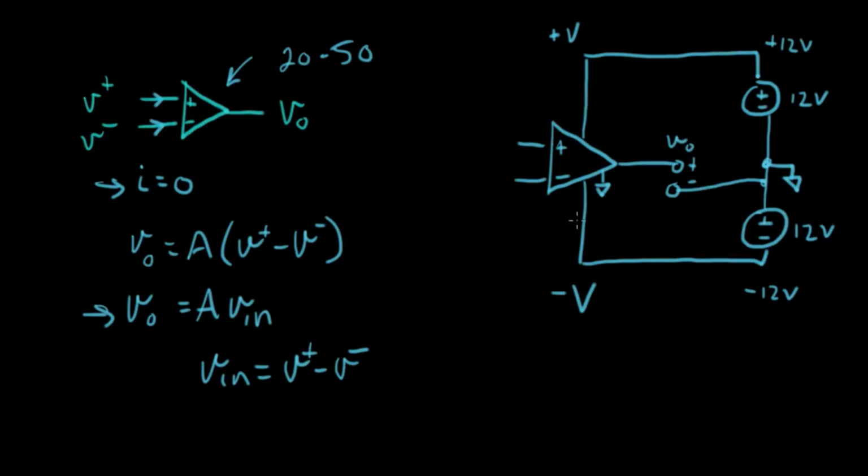What we're going to do is assume that all of this stuff is always hooked up, and we're just going to use an even simpler symbol, just the three terminals like that. You'll know that all the rest of the power supply is hooked up that way. The thing to keep in mind is there's a large minus voltage, there's a large plus voltage, and the ground node is right in between. Positive voltage is high on the page, negative voltage is low on the page, and V out can go both positive and negative around ground. So that's your voltage framework to keep in your head.